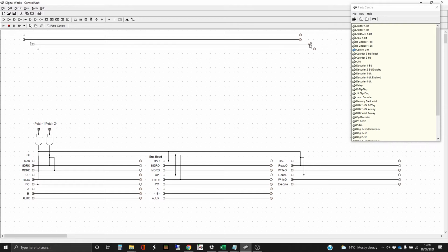If we need to extend it, obviously we can. And as you've seen, I've put a tag on one end, which is where we need to connect to an input, and I put an LED on the other end. This is just a habit of mine. We may never see these LEDs being used in anger because we might not be diving down whilst it's running, but it's there just in case, which will help us debug problems if we've got them later on. I'm very into doing defensive things like that.